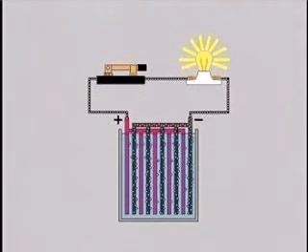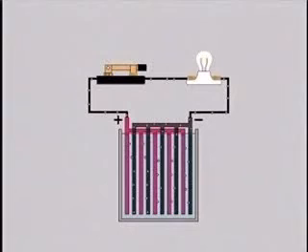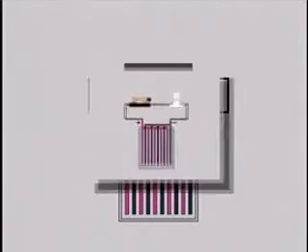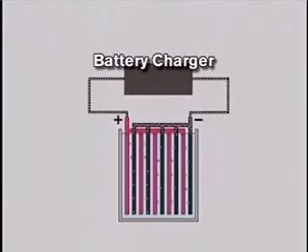Some of the electricity is transformed to other forms of energy within the circuit and loads, so the battery will begin to discharge. As it does, the chemical reaction inside changes the sulfuric acid to water, and the electron output from the negative terminal gradually decreases until the battery is fully discharged. Sending a reverse flow of electrons through the battery reverses the chemical reaction, bringing the battery back to its full potential. This is what occurs when a battery is charged by a battery charger, alternator, or generator.